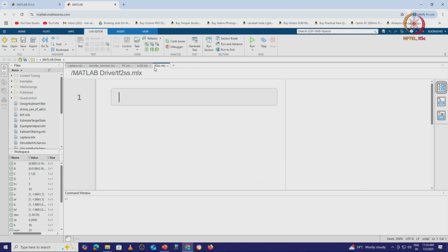So first we will see that if we have a transfer function, then how to change the system. Let's see how to define a system in terms of transfer function. We should have a numerator, right? So we take one system which has the numerator as [1 2]. What does that mean? It means that the particular system we are talking about has a 0 at -2, right? Try to think about it.